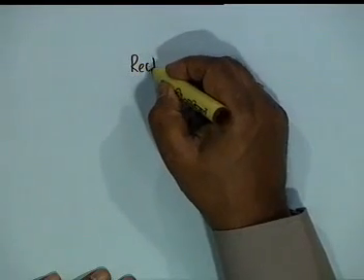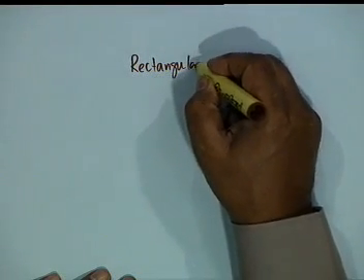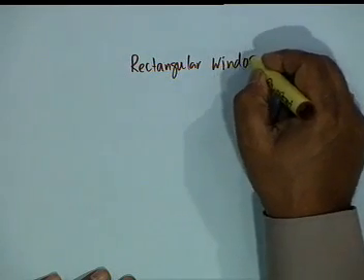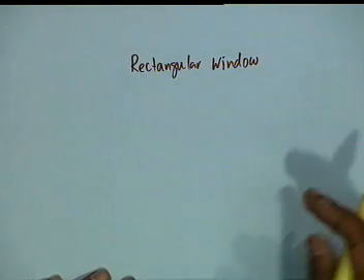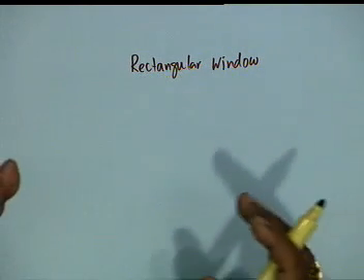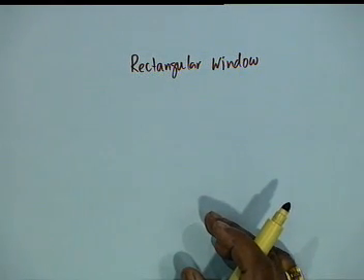Instead of the rectangular window, one of the reasons why this occurs is that the window itself is a sharp window, it suddenly rises. At n equal to -1 it is 0, at n equal to 0 it rises to 1, okay, and then suddenly falls. So people reasoned in the initial stages that if the rise and fall of the window is smooth, not that abrupt, perhaps we shall get better results, perhaps we shall be able to avoid Gibbs phenomenon to a large extent.